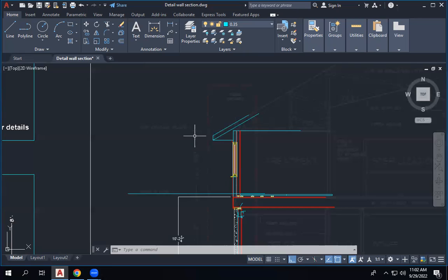When you are dimensioning, I saw some diagonal dimensions. You cannot put a diagonal dimension. You need to have vertical or horizontal dimensions, because if you are putting a diagonal dimension, you need to give the angle. Otherwise the person cannot measure. That doesn't make any sense.